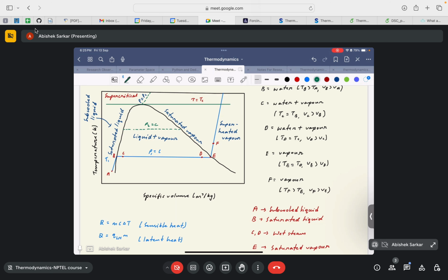That's the very concept of a pressure cooker, right? We pressurize the air above the substance that we are cooking and increase the temperature at which the water boils. So if we increase the pressure, the corresponding saturation temperature, the temperature at which boiling or phase change starts to occur, also increases, right?